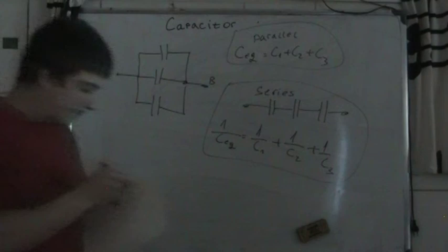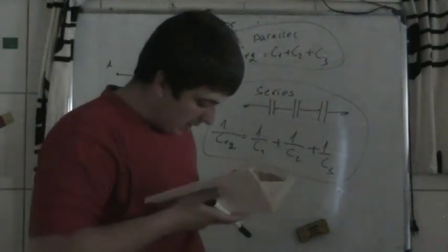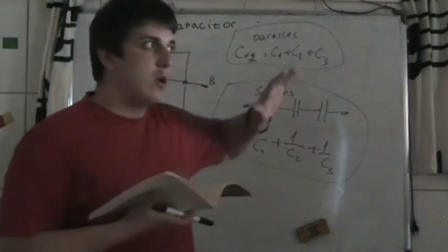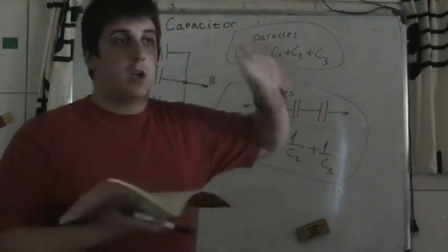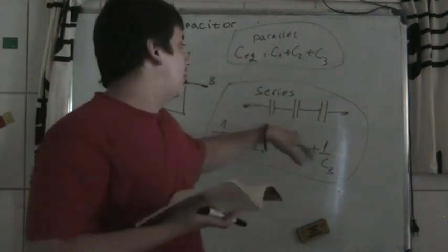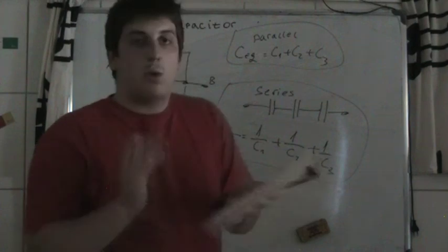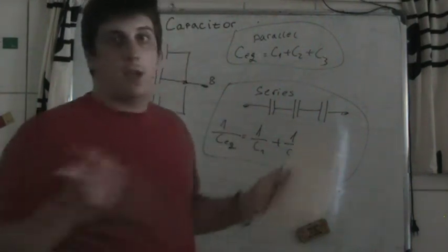If you want more capacitance, then you connect capacitors in parallel. If you want to lower the voltage on these capacitors, then you connect them in series.